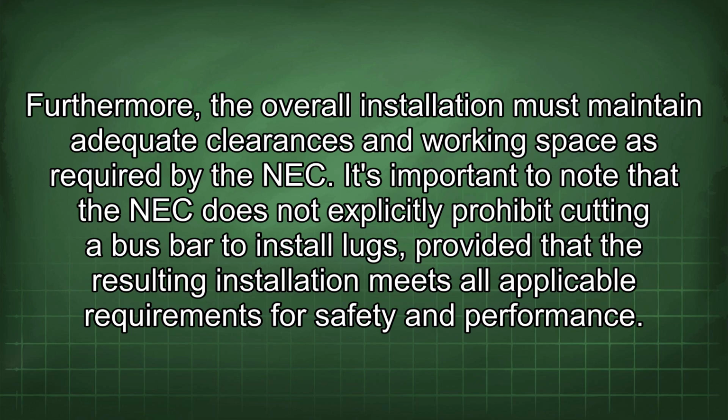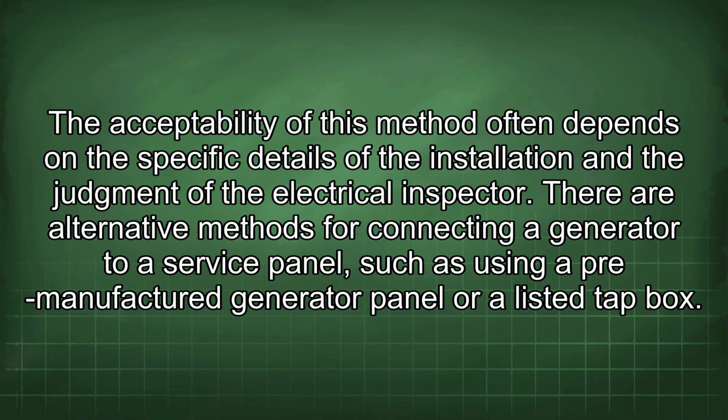It's important to note that the NEC does not explicitly prohibit cutting a bus bar to install lugs, provided that the resulting installation meets all applicable requirements for safety and performance. The acceptability of this method often depends on the specific details of the installation and the judgment of the electrical inspector. There are alternative methods for connecting a generator to a service panel, such as using a pre-manufactured generator panel